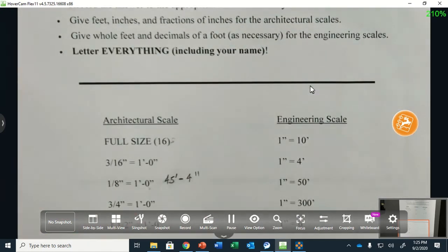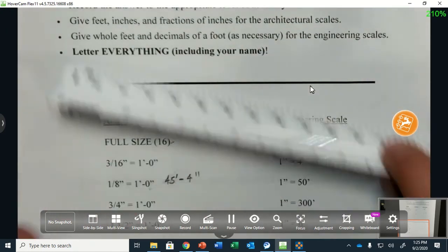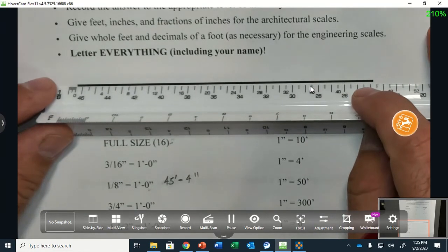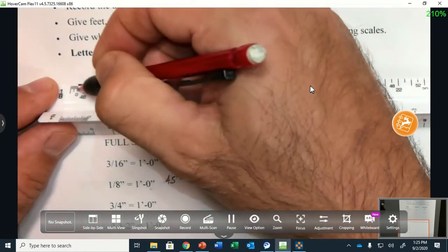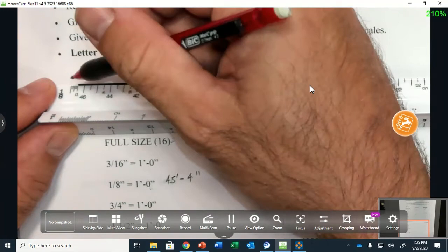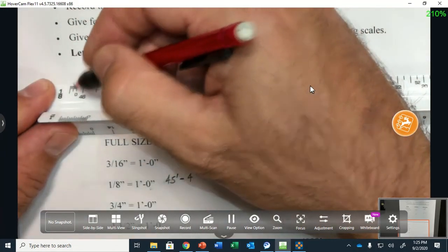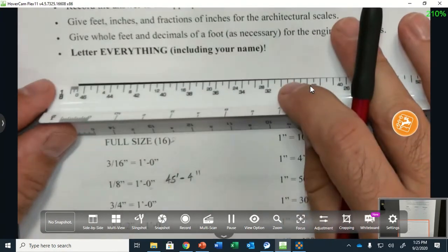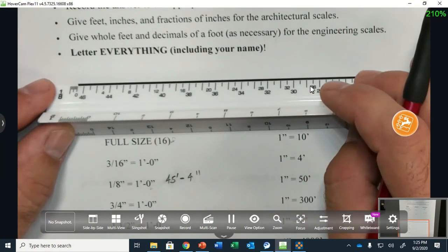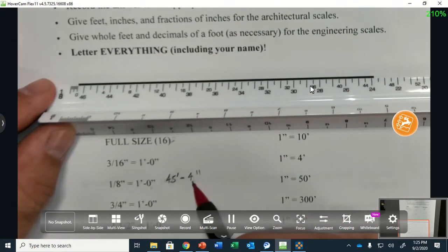All right. Because what happens? Right, I know each tick mark is 2. That's the first mental step you got to do. What is my tick mark? I know that's 1/8 inches, each tick mark is 2, so my accuracy is to the nearest 1 inch, half of the value of the tick mark.